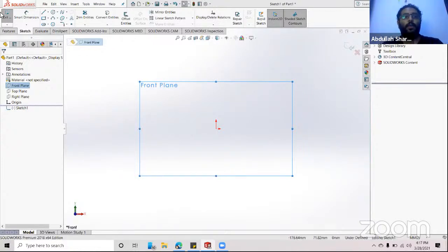So the first thing, we will try to get the tools. If I want to go out from the sketch after finishing, I will use exit here. Don't use the X. The X will take you out and will destroy everything that you have already done inside your sketch. I don't recommend using this one until the end. After you save everything, you can use it. Otherwise, don't use it. It's the same as this one, this X or this one, and this will take you directly out of your design.